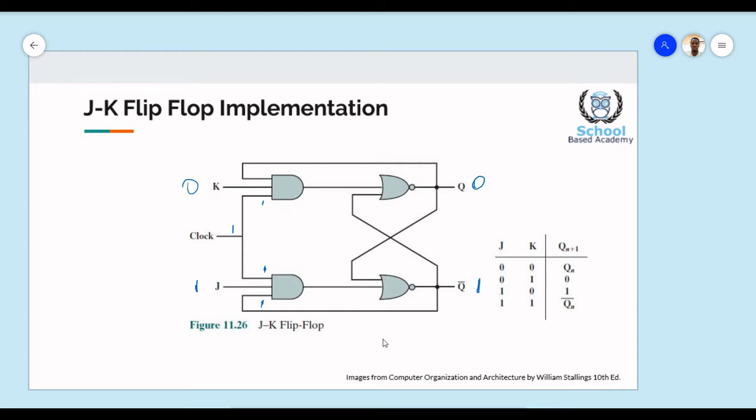And with all 3 gates providing 1 for us, we can go into this gate along this line, providing a value of 1 here. Now, with this value of 1 here, we have the value of 0 from the Q output, which is the current state of the flip-flop coming in, and we will take that value of 0 and pass it through our NOR gate, which will turn our value output of NOT Q to 0, which will mean that our flip-flop has gotten set to 1.